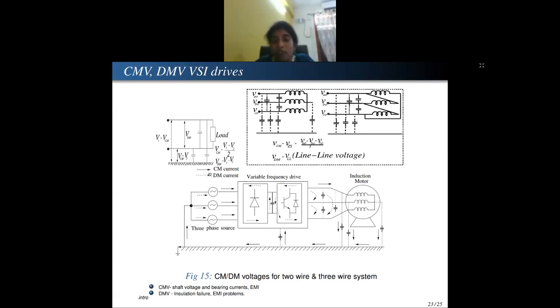So if you have a common ground, each wire will form a parasitic capacitance. So what is this parasitic capacitance? Why is it necessary to be present in the system? We'll see. It would be automatically formed whether you like it or not. Because if you see what a capacitor is, two conductors are separated by an insulating medium, correct? And this capacitor's presence would be realized if you have a voltage change across these two terminals.